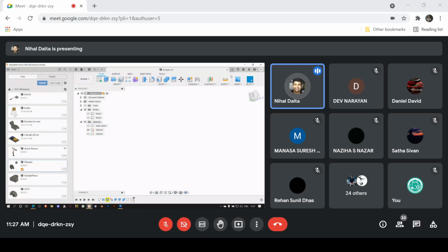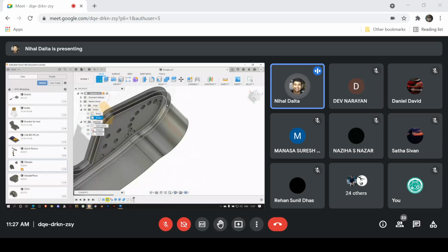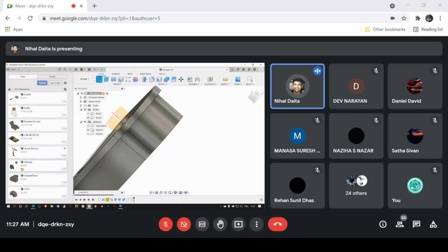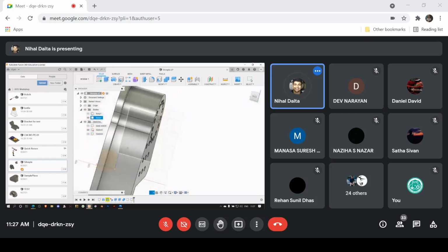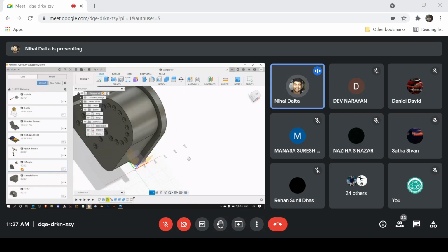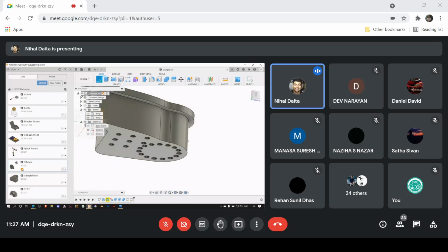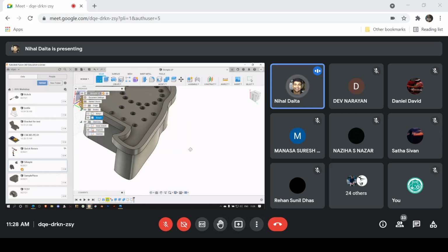So that will also give me an opportunity to show you these construct planes. As I've showed you earlier, you can either draw your sketches on these existing planes, or you can draw your sketches on a generated surface such as this, anything that's flat, that exists on a single plane. You can draw on those. You cannot draw on curved surfaces, I would assume. Yeah, you cannot. It is highlighting this flat surface. So you cannot use curved surfaces to sketch.